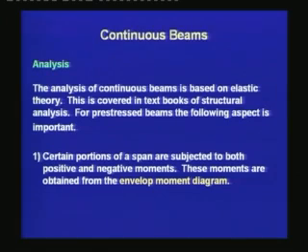Next, we shall study the analysis of continuous beams. The analysis of continuous beams is based on elastic theory. This is covered in textbooks of structural analysis. For prestressed beams, the following aspect is important. First, certain portions of a span are subjected to both positive and negative moments. These moments are obtained from the envelope moment diagram.